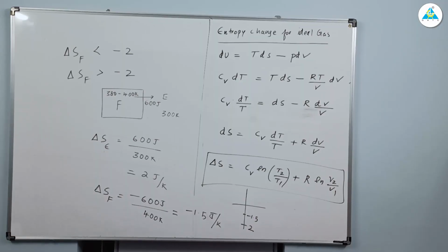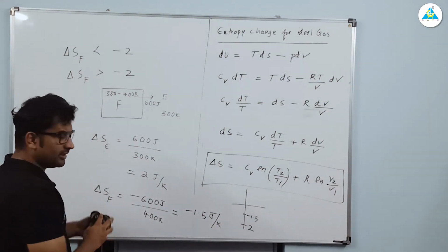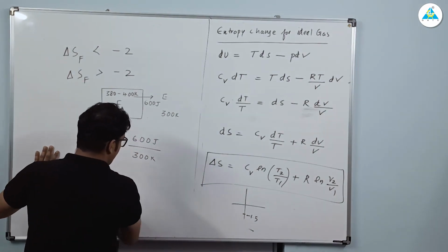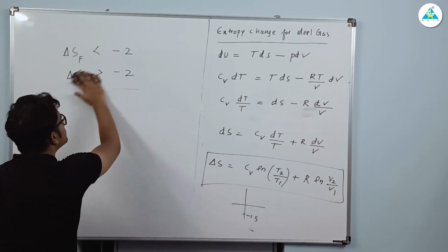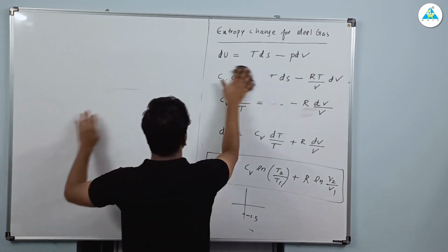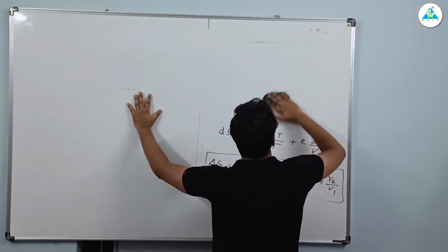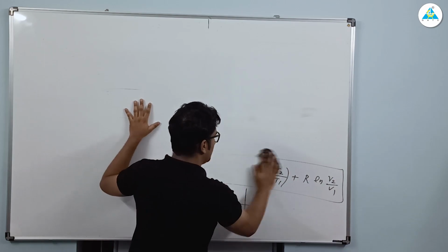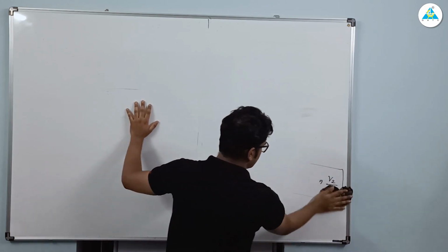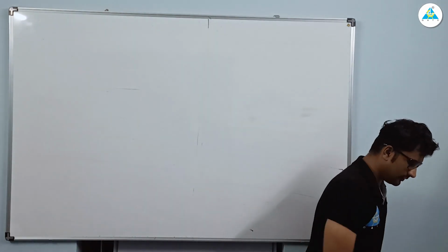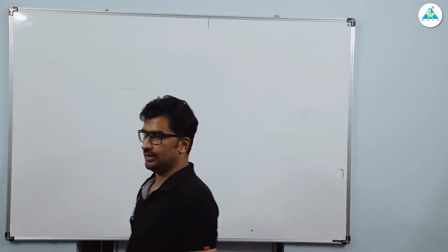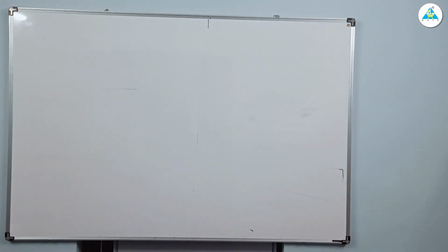So for those who couldn't read the question, you can pause the video and read it. But anyway, I will be writing the given values on the board. Okay, so it's a question based on a closed system, that's for sure, because it is a piston cylinder device, so it's a closed system, there is no doubt in that. Now you can see it's a compression process, right? Compression process, there are the things given. So let me first of all write the given values. Okay, so 2 kg of steam, so the mass of the steam is 2 kg, no doubt in that.